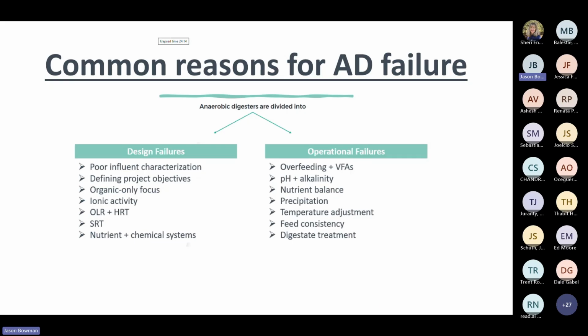Temperature is also a very critical part of successful digester performance, obviously. Almost all digesters are going to require at least mesophilic temperature conditions. So a lot of projects actually fail to account for proper heating, or fail to account for the fact that you have to utilize a portion of the biogas being produced to provide enough heat to the digester to make sure that it's always in a mesophilic range and to keep your removal efficiencies at a high level.